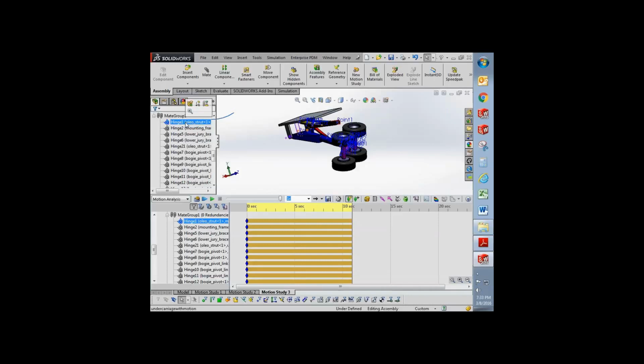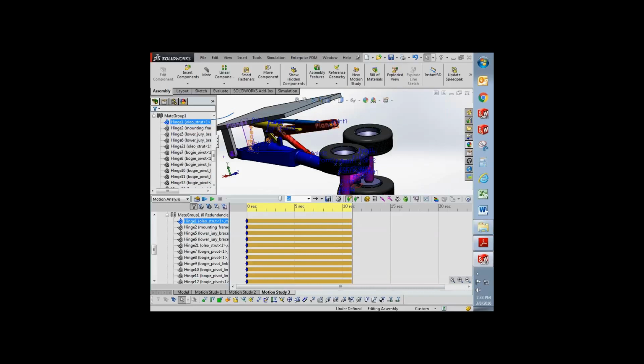So with hinges, I needed a point on a plane for coincident and on two axes or two concentric faces to keep it at 5. So that's why I created those points. It's just my way of mating. It also helps me organize my things. So that's why all these points are used for those hinge mates.